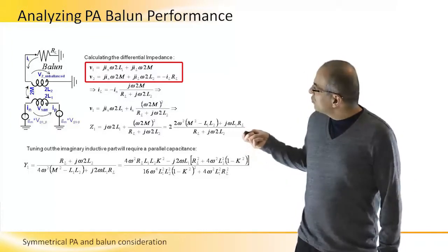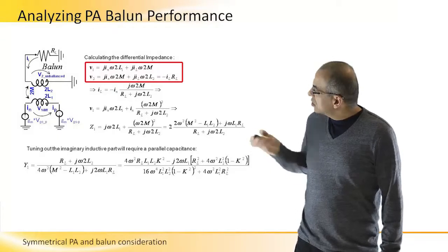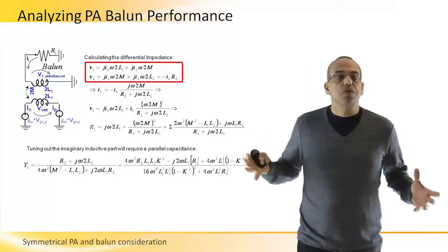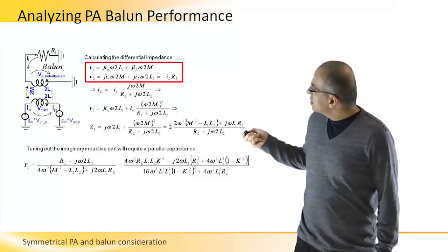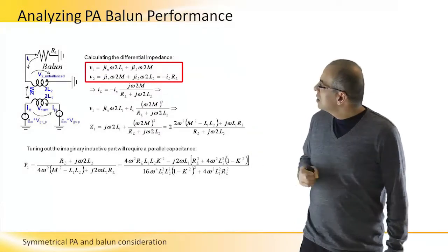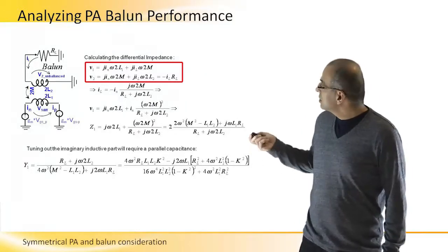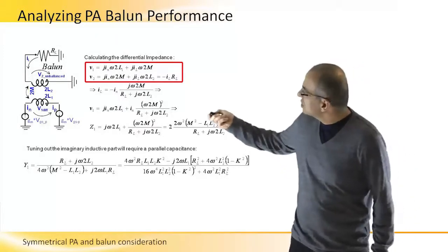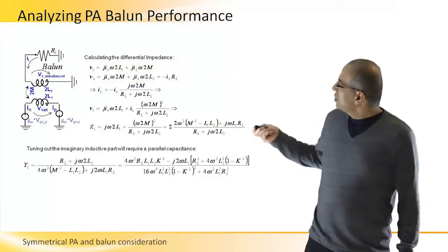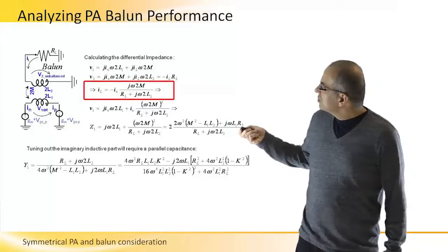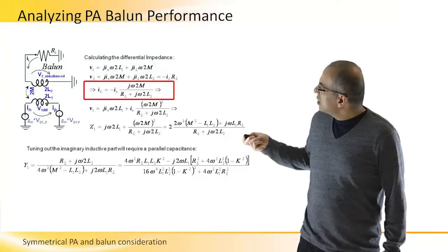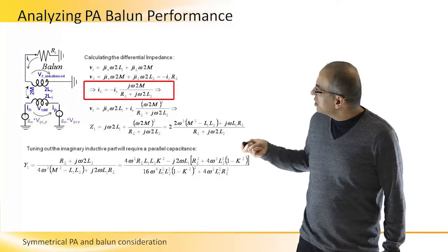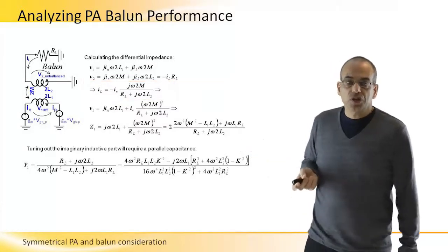When we look at V2, which is the voltage across the output equivalent circuit, we can remember that it is equal to the load current times the load resistance, with a negative sign. We can see it here in the output. And we will use this expression to express I load in terms of the input differential current.